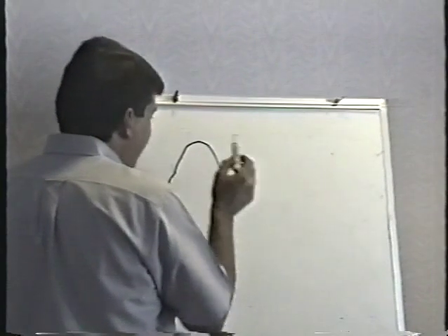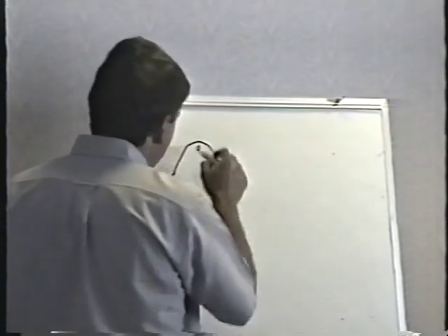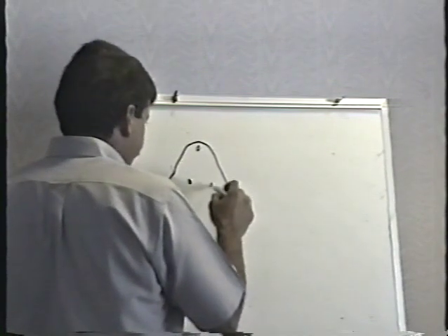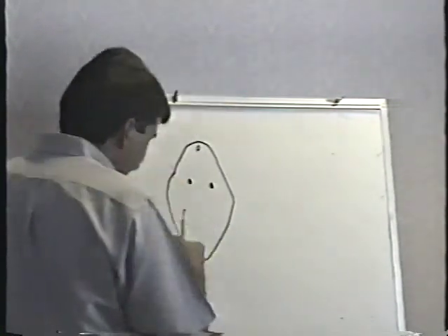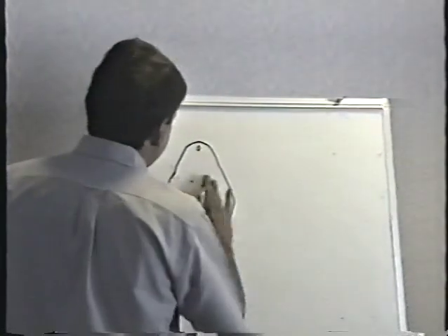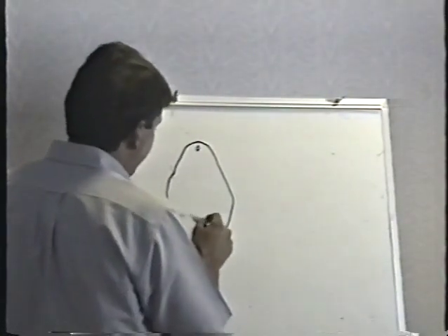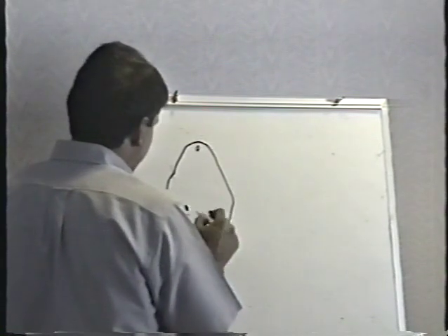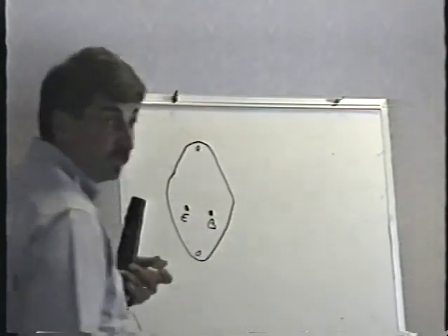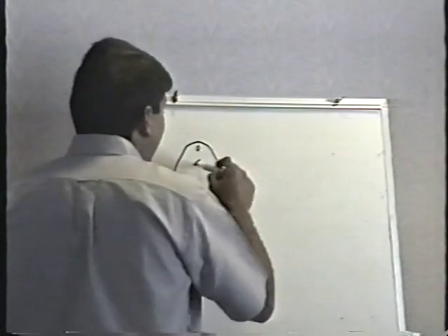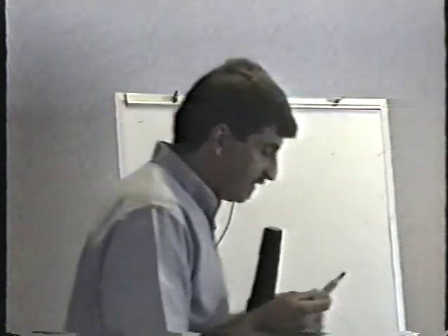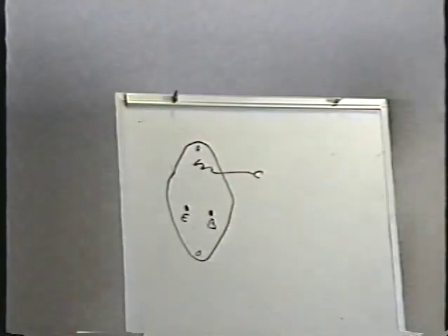In this particular case, they're labeled, but they aren't always labeled in all these transistors. If you hold it right side up, the one on the left is the emitter and the one on the right is the base, right? The collector is the case of the transistor. The metal case of this transistor is the collector.